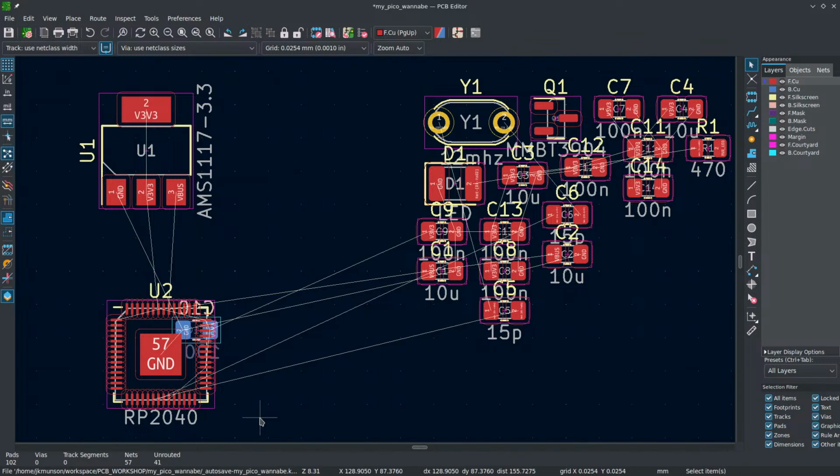If you take a computer processor from AMD or Intel, the older ones I guess I should say, and you flip it over, you'll see there's a whole bunch of capacitors there. You'll see that's what they're doing. If you have a motherboard, on the backside of the socket, there's tons of capacitors right there. Yeah, and that's just about it. It's a good place space-wise. It minimizes the distance that current has to go through them.